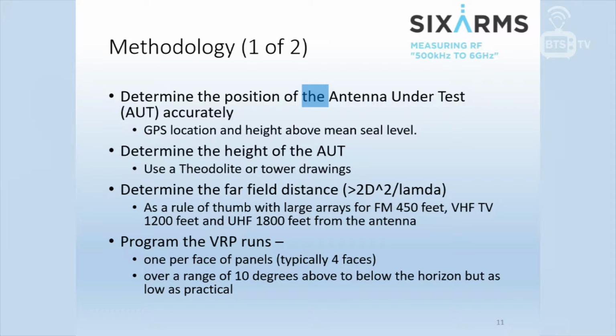We need the height of the antenna that's under test. Generally we'd use tower drawings, or if that's not available, then we'd use a theodolite to pick up the centre height of the antenna that we're going to test.